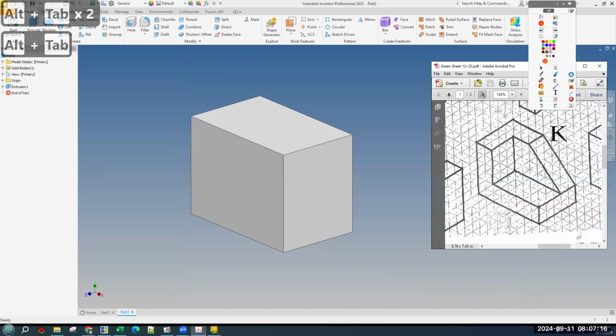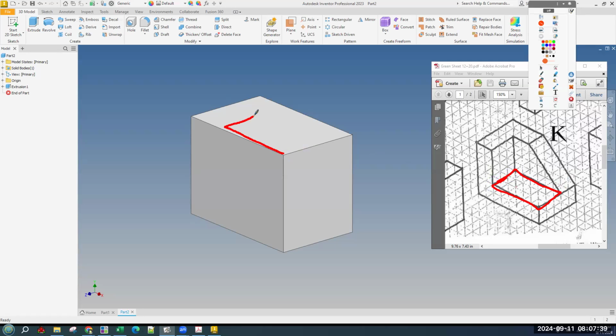And let's cut away everything that isn't the sculpture. Okay, so we have 2 more part features required because these are different types of extrusions in different directions. We can't do them at the same time, which is fine. We need to cut out this shape. In order to make this shape, or one way to make this shape, is to make a rectangle on top, the correct size, which would be up here, and then cut extrude it down to make this surface.